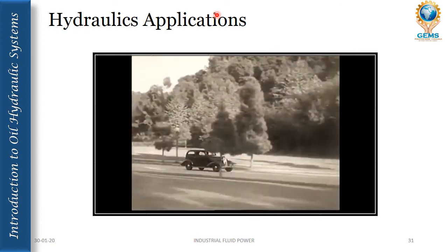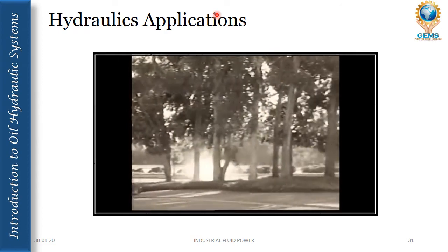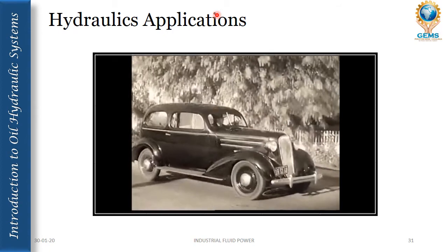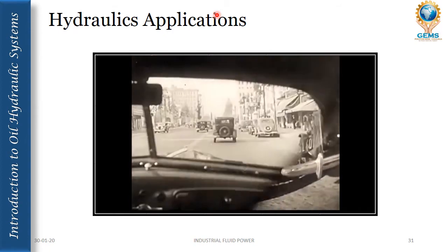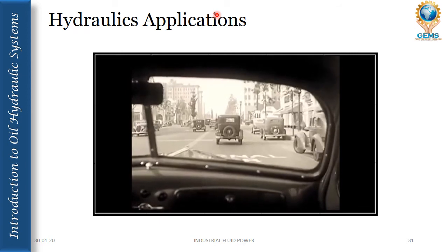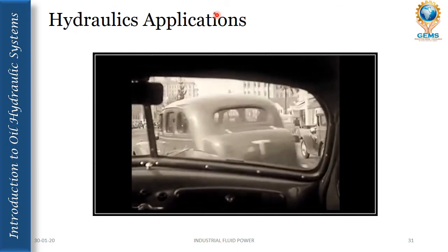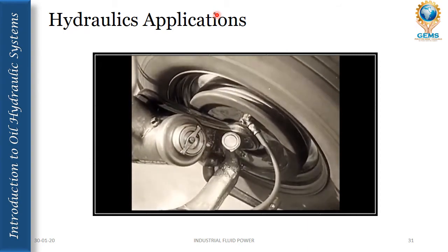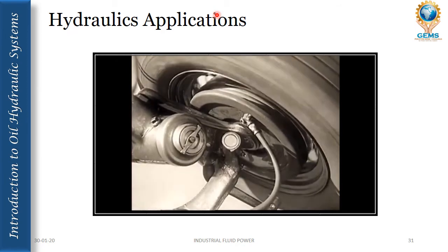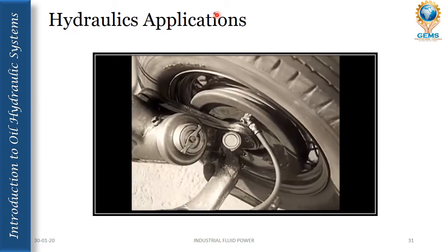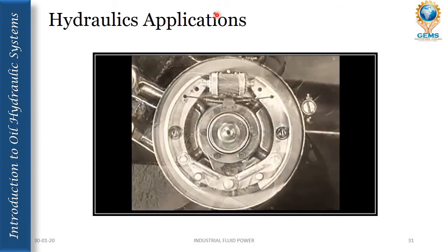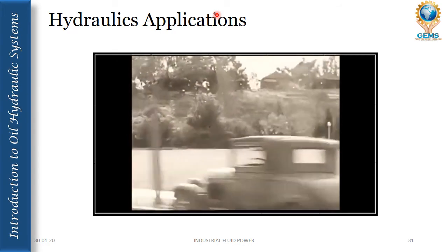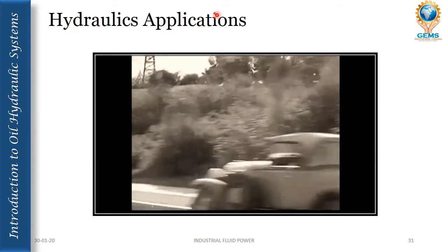A car that takes 90 horsepower to go from a dead start to 60 miles per hour in 20 seconds can stop in 4 seconds, but it takes 450 horsepower in the brakes. The final safety and control of the car depends on the construction of the brake itself. It is the brake itself that stops the car, not the hydraulic control. Perfected hydraulic control transmits the power from the foot pedal to the brake itself and gives you the sure, quick stopping safety of the modern automobile.